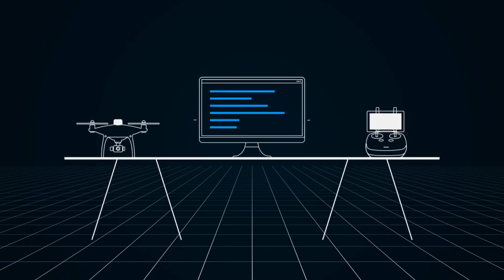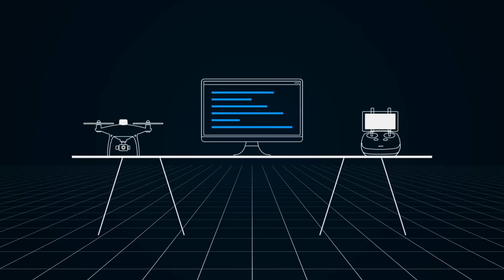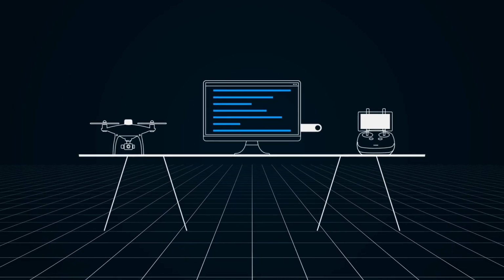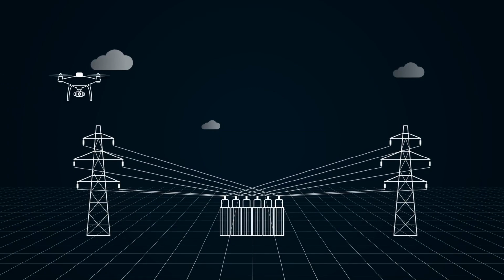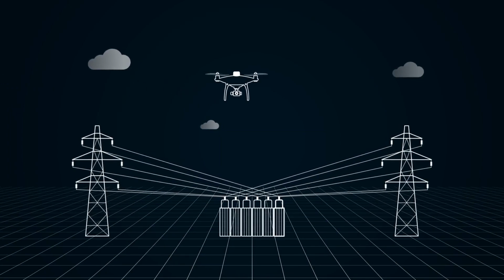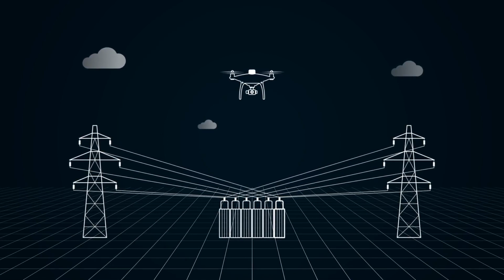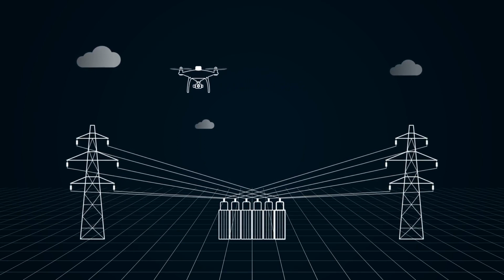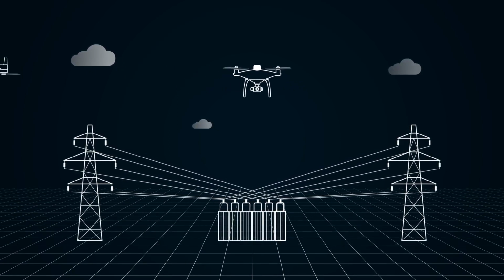In order to make it easier, Network PPK Solution Service is developed in recent years, and the differential data solution can be completed by simply uploading the data collected from the aircraft. When a drone enters areas with high electromagnetic interference, such as areas around electrical substations or iron ore, its compass may get disturbed and the drone couldn't calculate the direction it is pointing, which will usually result in the drone being unstable.